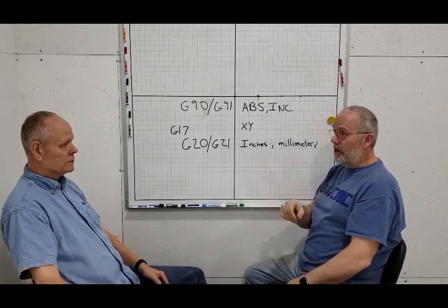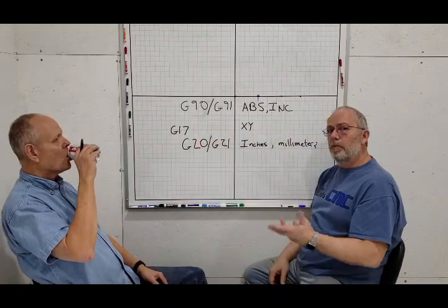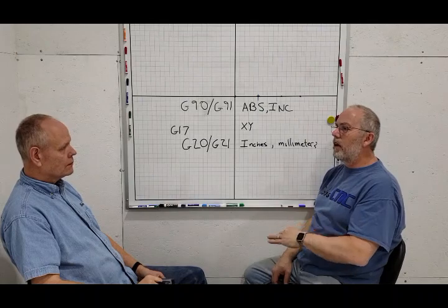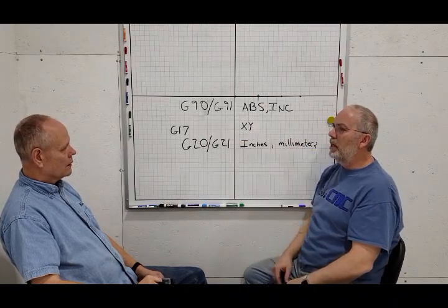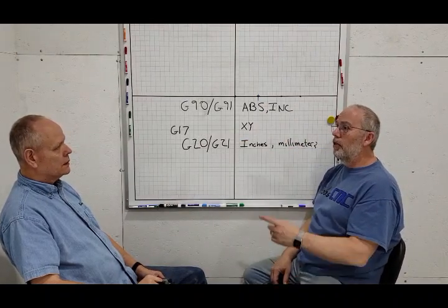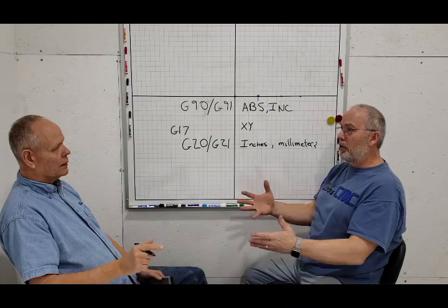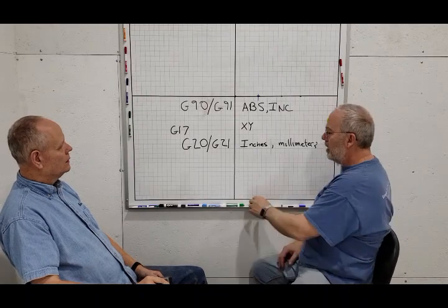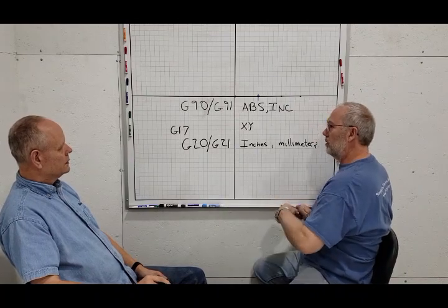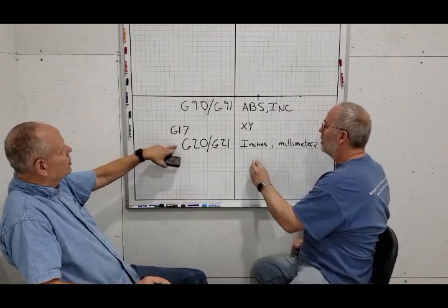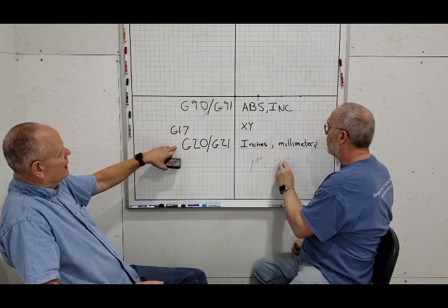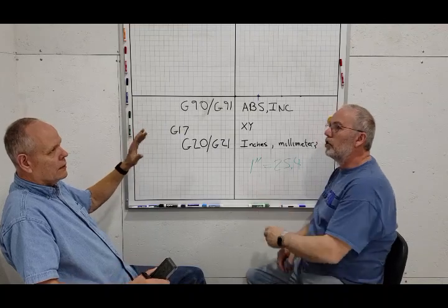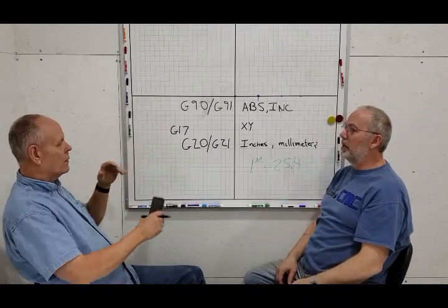However, you might note that if it's missing, different programs default to different units. Universal G-Code Sender defaults to millimeters. If it's missing, it will be done in millimeters. So if your work is actually 25.4 times smaller than it should be, you probably know. Because 1 inch is 25.4 millimeters. So if this is not in your code and you want to do something in inches, Universal G-code Sender will do it in millimeters.